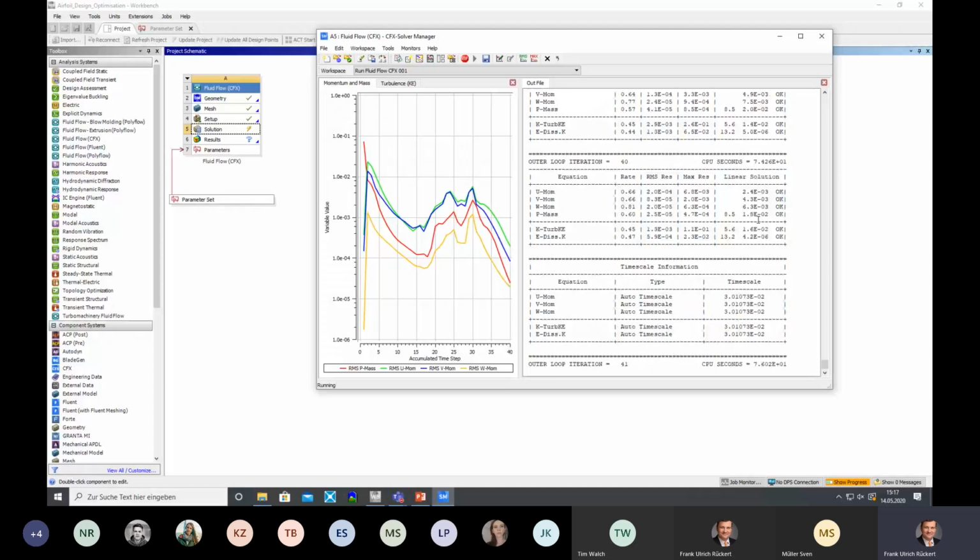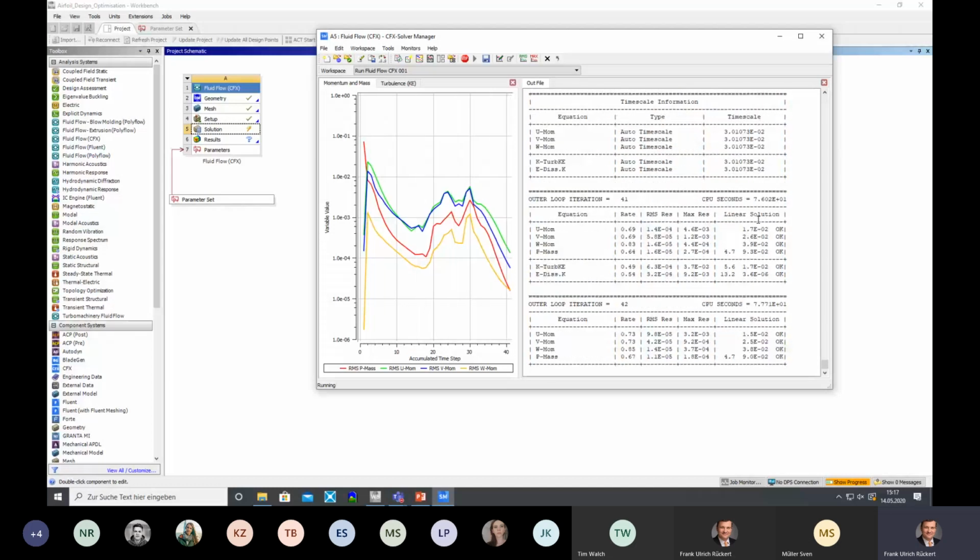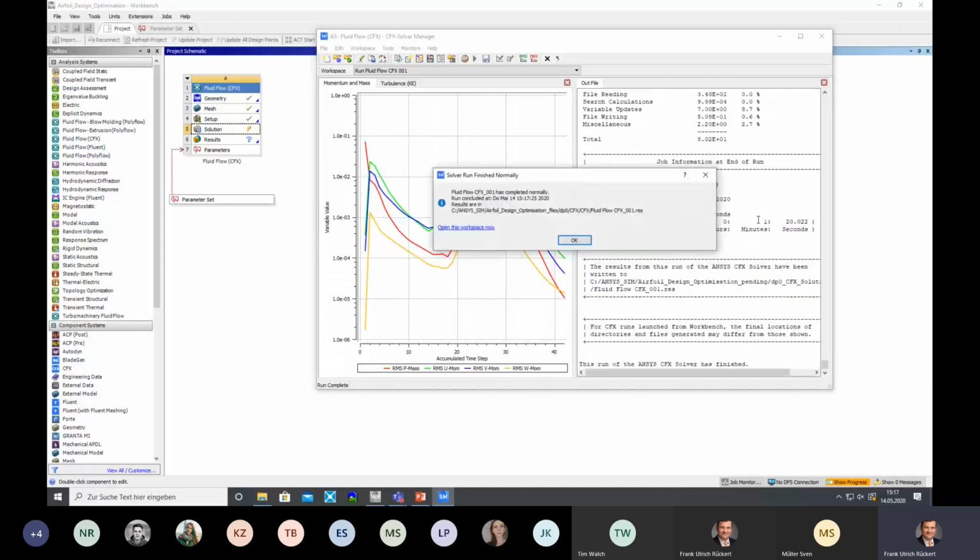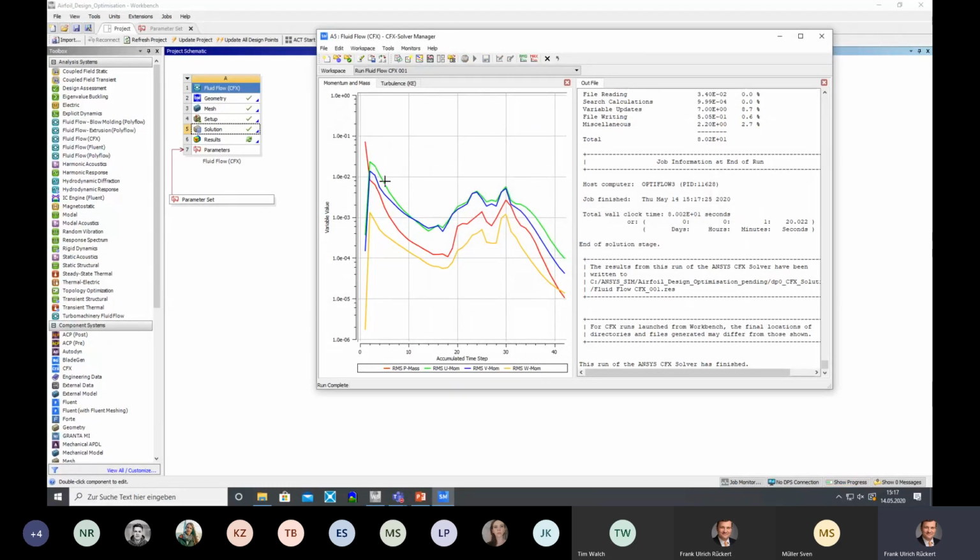But now it goes down again. Yeah, I think this behavior, this solution of the Navier-Stokes equation is something new. You see, first the numerical simulation converges, then it rises up again, and then it converges again. But I can tell you why this effect happens. It's probably because we have defined the walls at the sides also as surroundings, and this will have some turbulence-like effects that cause the rise here in the convergence.